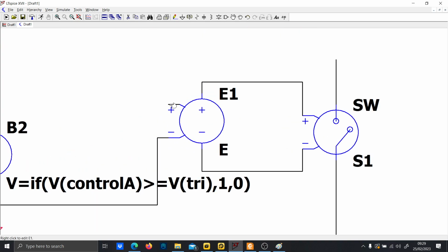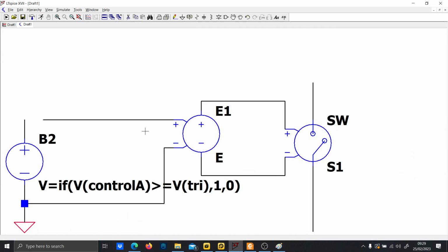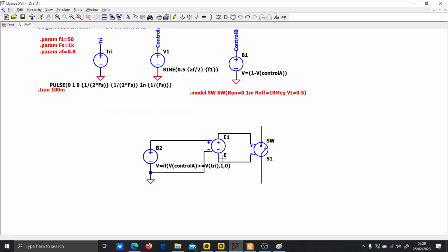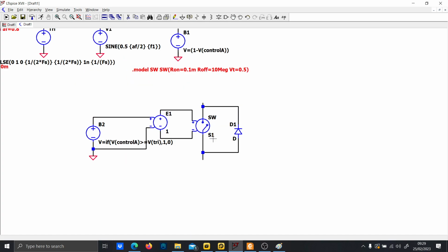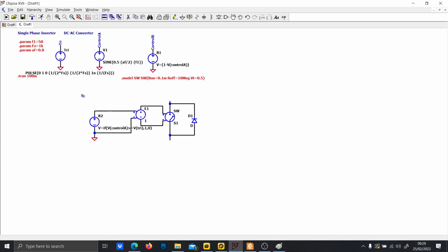I don't understand why there is a node here. There should be no node. Okay, now this is correct. Let's put the gain as 1, and let's also put a protective diode here. This will be our ideal diode, and basically the circuit is finished, because now what you need to do is to replicate this 4 times.